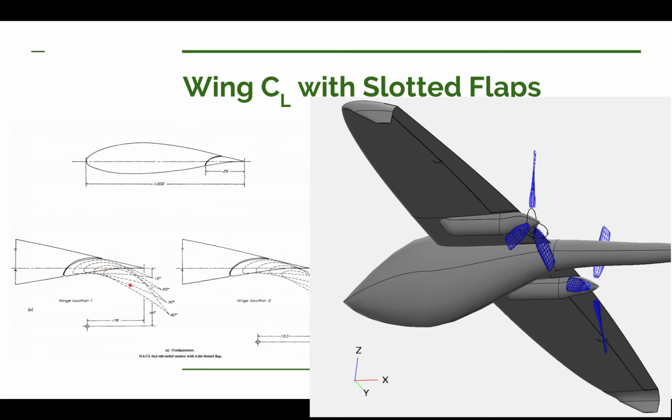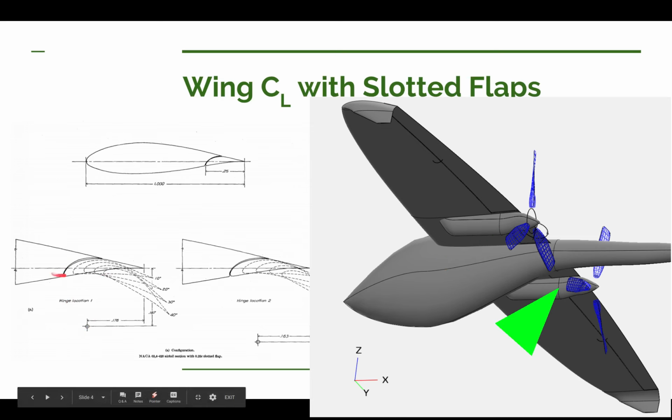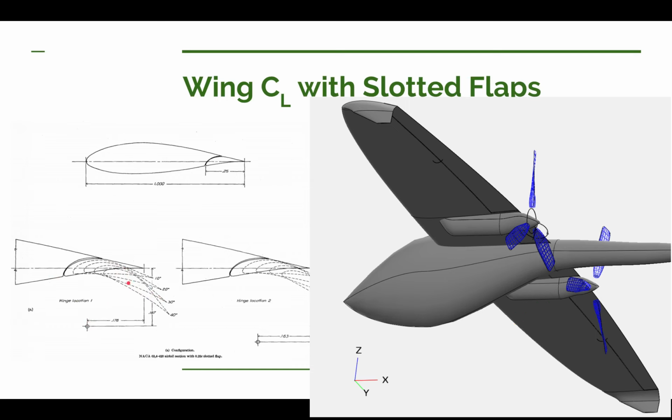Another thing that we can take advantage of is we plan to have the engines attached underside the wings on some nacelles. What we can do is make sure those nacelles drop down far enough that we can use the side of the nacelle for our hinge. So once again, we don't have to have anything dropping down from the wing. The nacelle will replace that, and we can fare, just like against the fuselage, we can fare the connector between the hinge and the slotted flap into the side of the nacelle. So at least at cruise, we don't have drag.